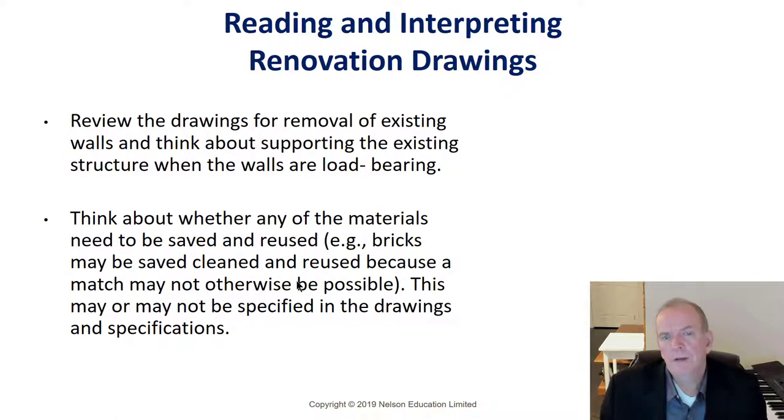You have to think differently with renovations too. You can't necessarily get the materials that were on the old house. So things like brick and things of that nature, good luck at trying to get an exact match. Now, if it's a new addition, maybe you can get something close, and maybe you could put a rainwater leader over the joint so it transitions from one brick to the other fairly well. But there's always going to be differences in the coloring of the brick, even with dye lots of bricks that are made today. If you get one from a different dye lot and you put it on a house, 2 dye lots can look quite different. So you have to be careful about that.